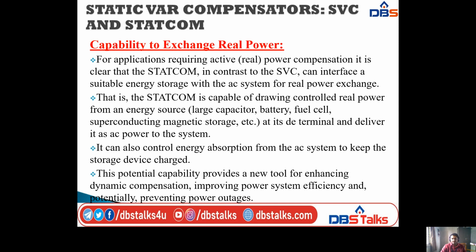That is, the STATCOM is capable of drawing controlled real power from an energy source or active power exchange. The energy source is a large capacitor, battery, fuel cell or superconducting magnetic storage, etc. We use the energy source for controlling the real power at its DC terminal and deliver it as AC power to the system.